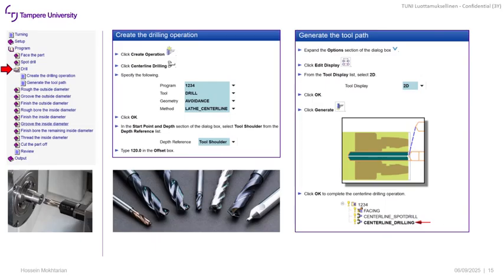If not, for example, we could use a drill diameter of 15 or 16 and then leave 3 to 4 millimeters to have two passes of finishing to reach the intended surface roughness. As you know, you can reach a better surface roughness by using an internal cutting tool with the specified parameters that you can figure out from the process parameters that you extract from the tool catalog, and depending on the material, of course, you can reach a better surface roughness compared to when you are only drilling. But in this case, as I said, we are only going to drill.